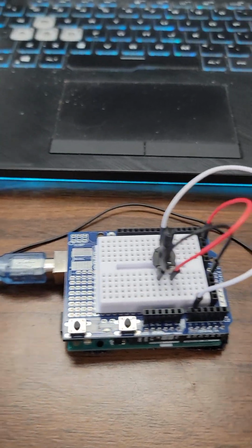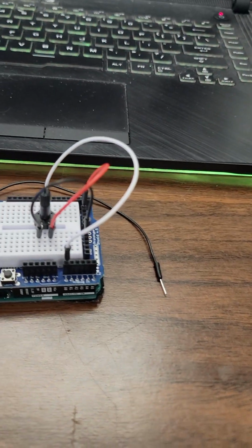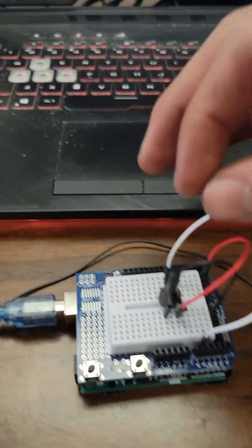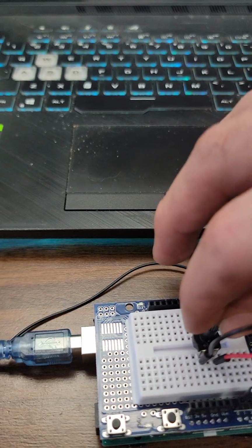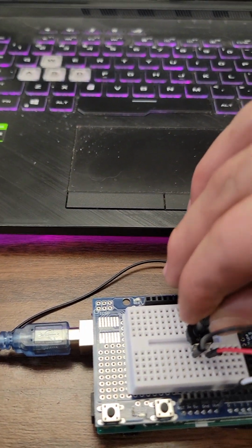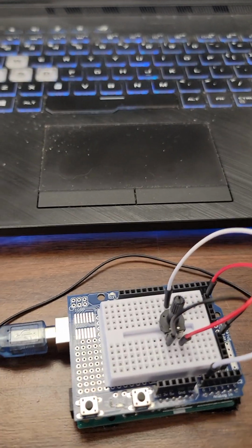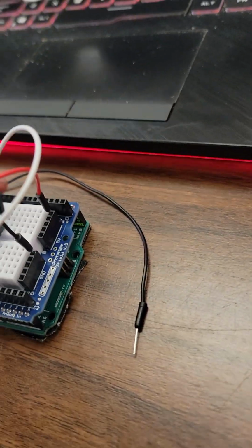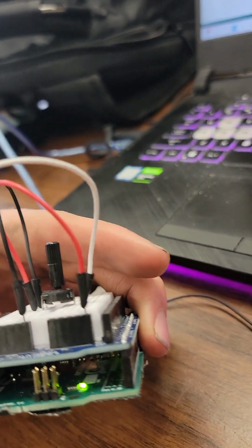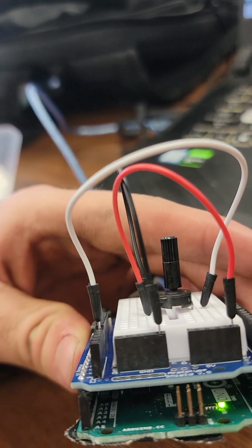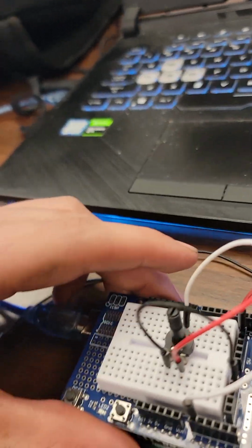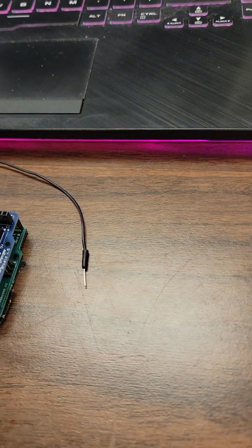So at a value of 0, that means that resistance is at a maximum and we are having no voltage across the resistor. As the resistor decreases in value, we will approach 5 volts coming out, or a 5 volt potential across the resistor. As we can see, we have the red wire at the 5 volt pin, black wire is ground, and white wire is the analog pin.